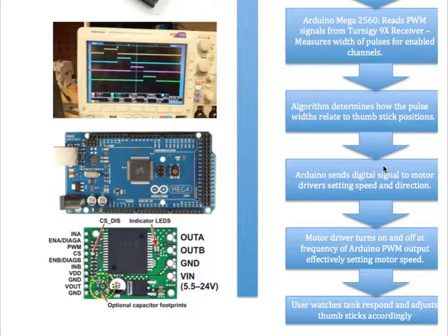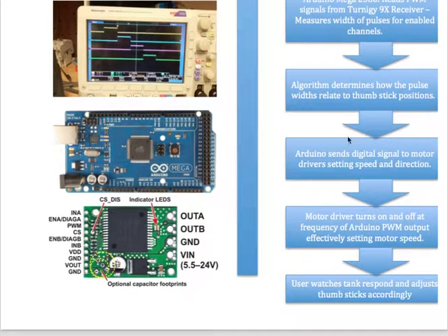The huge advantage to PWM is that even though the motor's only seeing 12 volts on average, in actuality it's seeing a peak of 24 volts and a minimum of 0 volts, which means we still get the full voltage applied to the motor during the on times, and then during the off times we're just off.